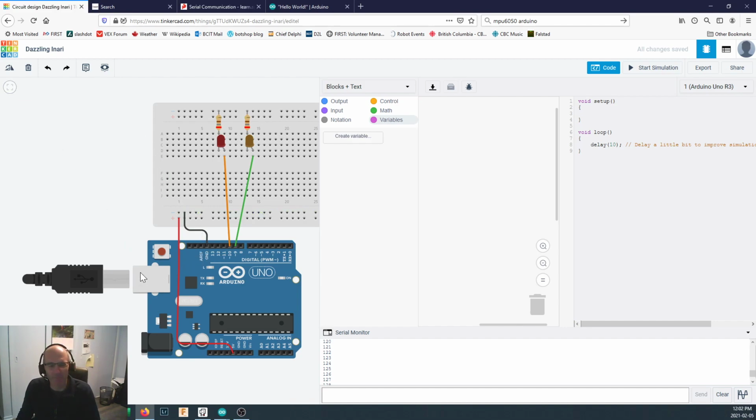So we're going to send those bits, which are either on or off, down this line right here. Now, the Universal Serial Bus Protocol, and the protocol is basically the language, the commands, the rules that the computer uses to talk to the Arduino, is a fairly complex one designed for high-speed communication. And you've got a little chip on your Arduino right here. On brand name Arduinos, it's actually another Atmega microcontroller, but on some of the less expensive ones, it's a little chip called CH340, and you have to have a special driver installed for your CH340.